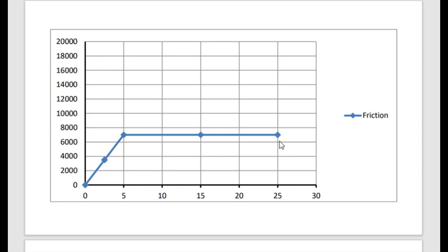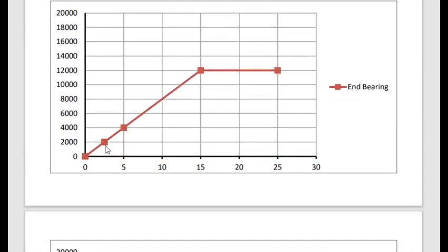What is this point? It is the load corresponding to failure and the start of the failure settlement. So it's when I added 7,000 kilonewton or ton, and then I got a settlement of 5. It started with 5 and it ended with 25. It did not stop. So if you give me this point, I can draw this friction line. Okay? Go to the other one.